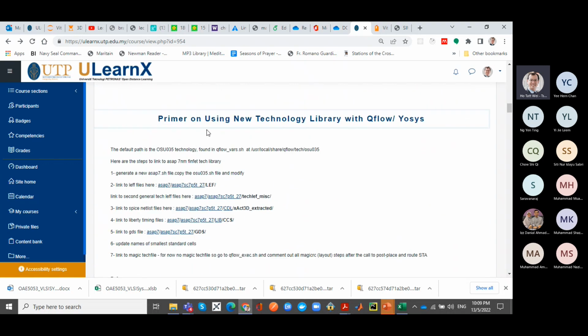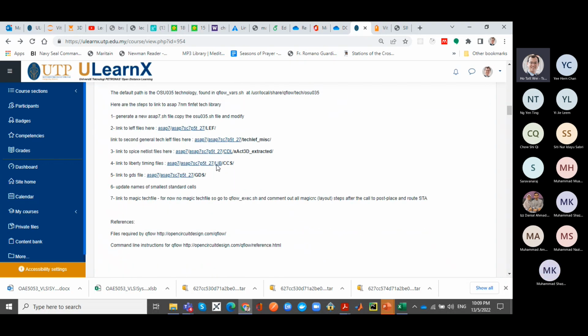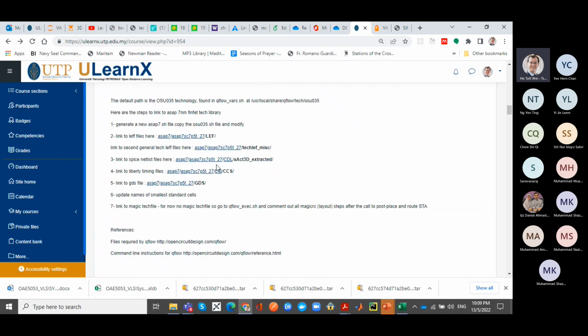And then the technology library is very important. Let's say you're making a chip. Normally, your team will say, okay, we're going to use Intel Fab, what process, or we're going to use TSMC in Taiwan, the Fab, what process. So that process, or sometimes they call it the process technology, refers to the set of logic gates that's available to you, and the Fab has a detailed characterization of that. Usually the model of those logic gates, the timing, is given in a file called the Liberty file, with a .lib extension. Here I am giving you two Liberty file examples.